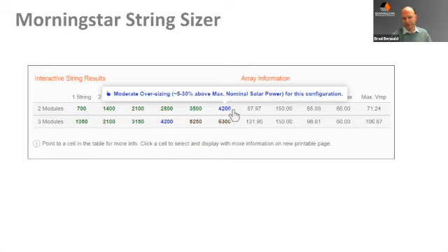But like with standard grid tie sizing practices, you'll often find that putting more wattage on the controller than it is designed to handle continuously is a pretty good design practice, because you can see more power generated during lower levels of solar insolation. So you might actually get more consistent power or more total throughput, and it allows you to best maximize the controller, which is a critical part of the system, and one that you may not have the ability to expand as easily and cheaply as you can with a solar array, which are reaching new cost lows. Okay, so system sizing is an important one to cover when it comes to the string application.